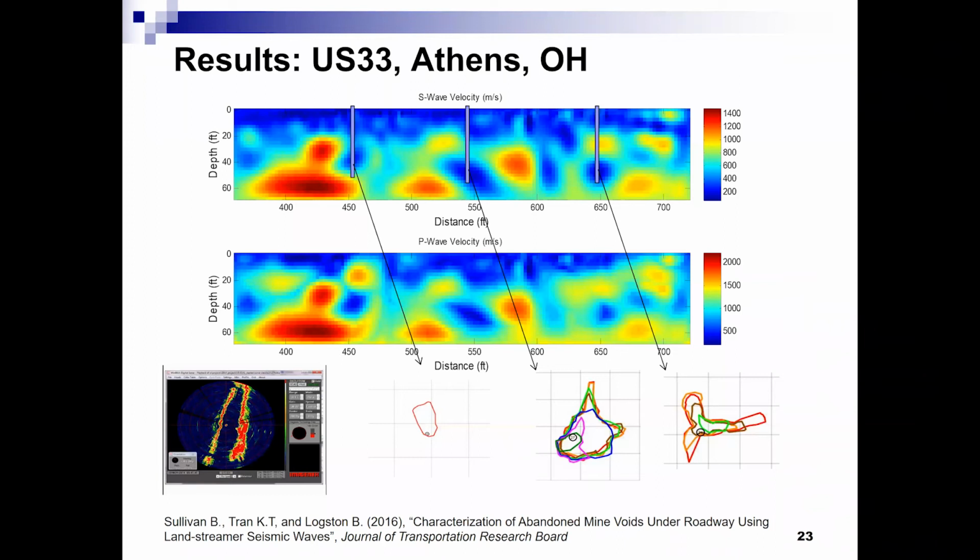Usually, many times we will miss it. But in this case, we did it very well. They drilled it and found the void, and they also did sonar scanning to identify the boundary of the void. Sonar scanning is similar to this. They measure the travel time from the borehole to the edge of the void, and then divide it by the velocity to calculate the distance.